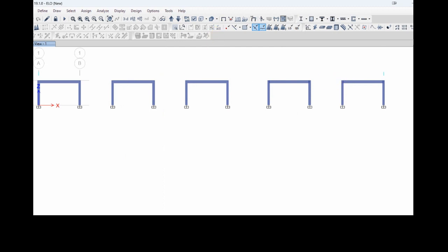So the frame element may overestimate the deflection of the structure in some structures. This is due to the stiffening effect, which we have discussed just now, caused by the overlapping section at a connection, and it is more significant in concrete than in steel structures, as we know that RCC structures have huge cross-sectional elements, so it is likely to be significant in concrete rather than steel.